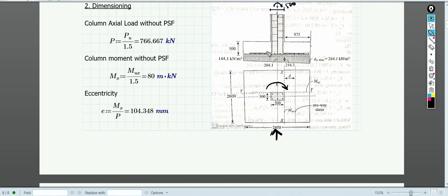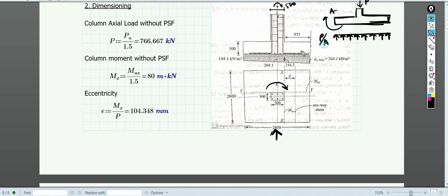Now, I don't know whether you have learned it or not. Whenever we have a footing, if I give a point load to it, suppose we have a footing without any moment and only point load P. I think in the column part I have discussed this portion. Then the stress from the soil will be uniform, just a rectangular type, right? If A is the cross sectional area, then it will be P by A, right?